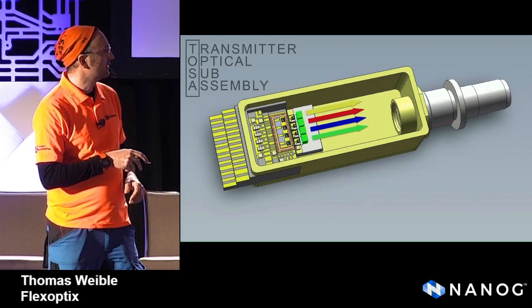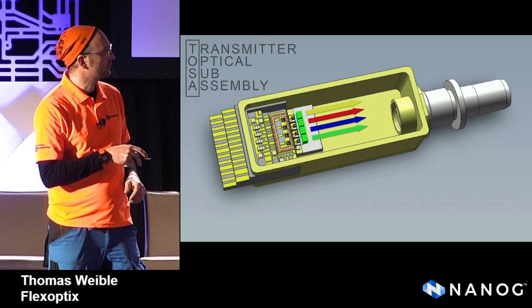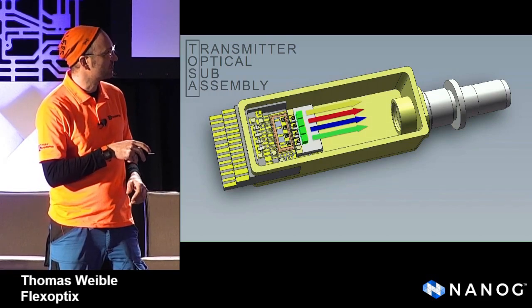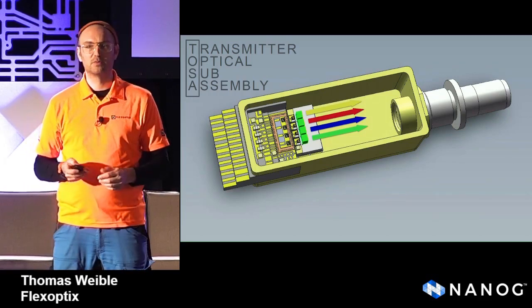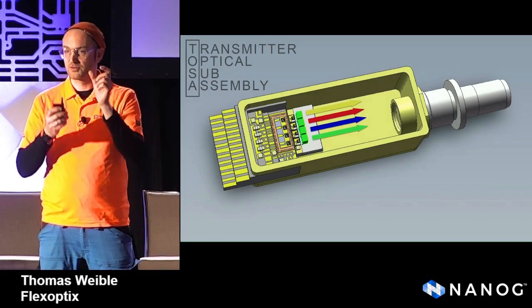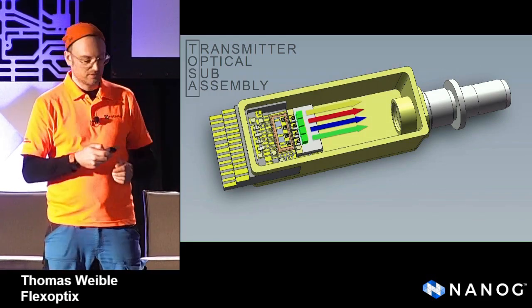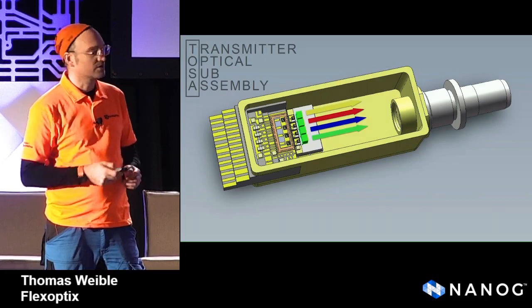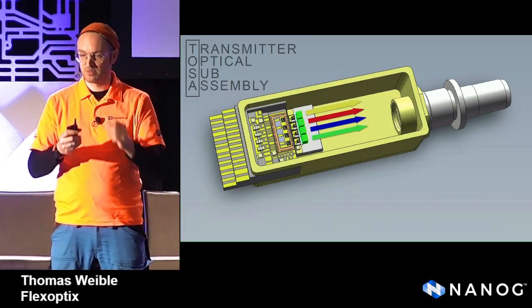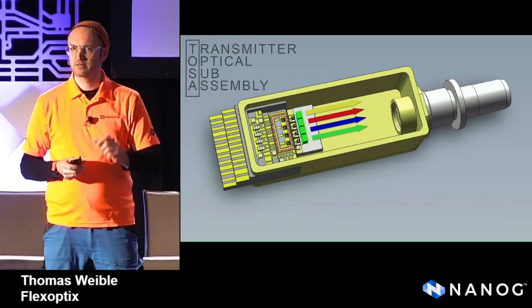So what we have now is focused light coming out of those 4 lenses, but actually they would hit the wall here, and we need to insert them into the receptacle. This is the typical receptacle for an LC plug, and now you can also see the dimensions. That's the receptacle where you plug in the LC plug, and it's quite big here on the screen, but when you see it in the real field, it's a tiny part.